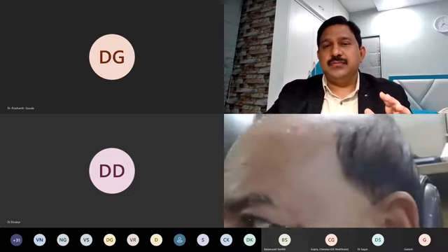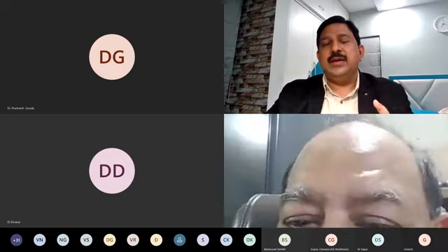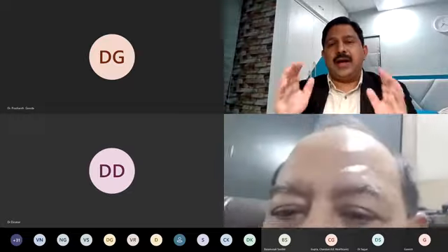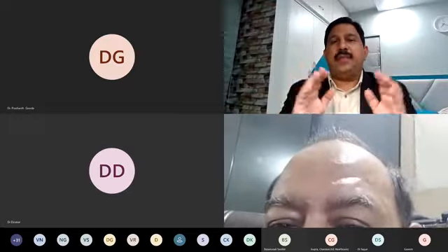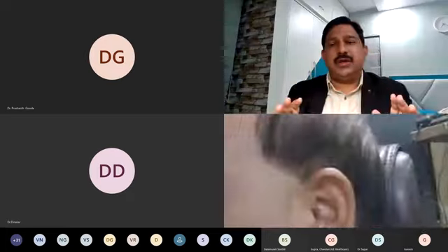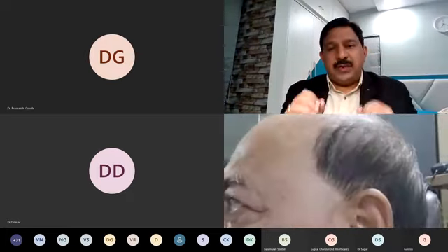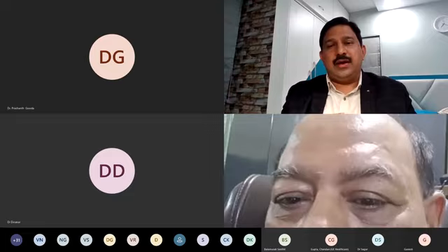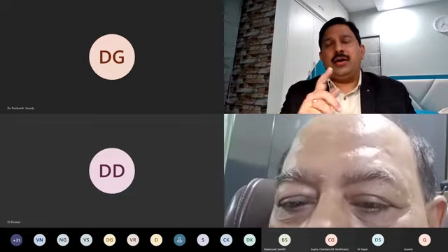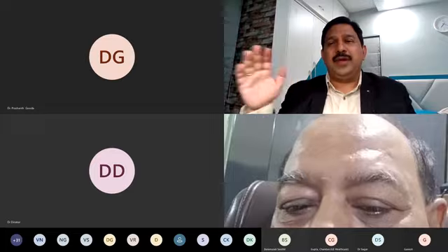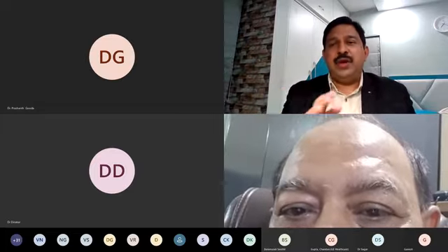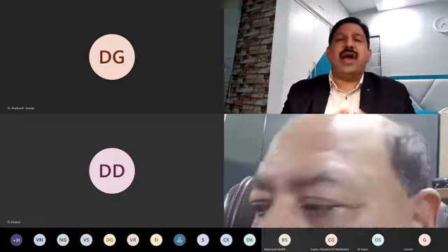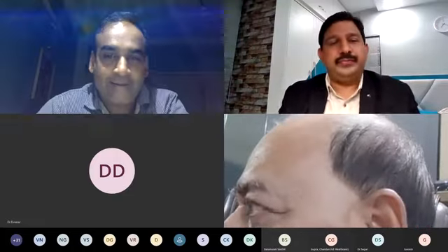We are putting each and everything other than medical equipment like CT, MR, LINAC, or cath lab on it. PET CT is not there. They have their individual UPS. Other than that, our emergency lighting is also on UPS. All the PCs are also on the UPS, and all equipment like endoscopy and dialysis. We have a 16-bed dialysis, that is also there. So in 160 kVA, I am using 70% of the load.